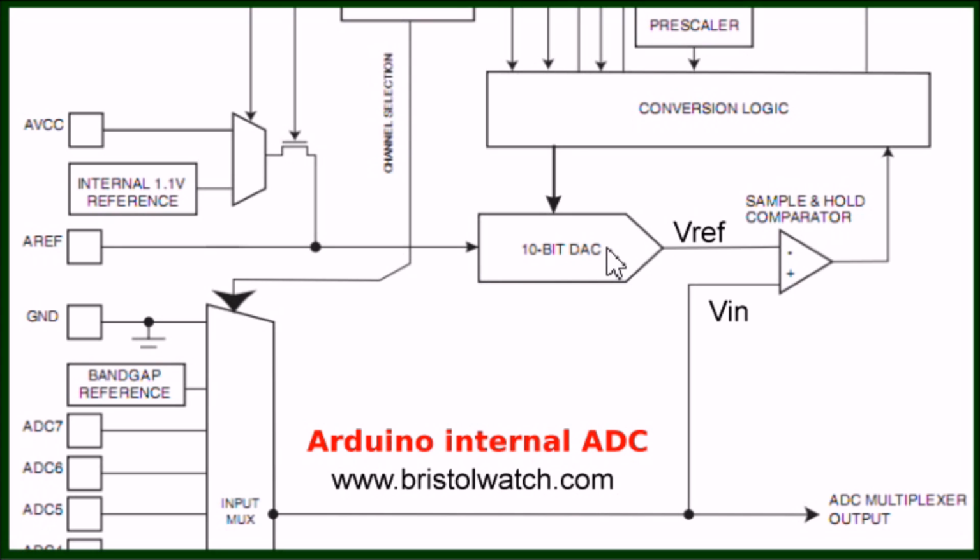It varies the output voltage on the DAC, and it looks for the relationship where the output state change on the comparator is going to signal the conversion logic, hey, I have a match. It depends on how it works. There are different ways that these could work.